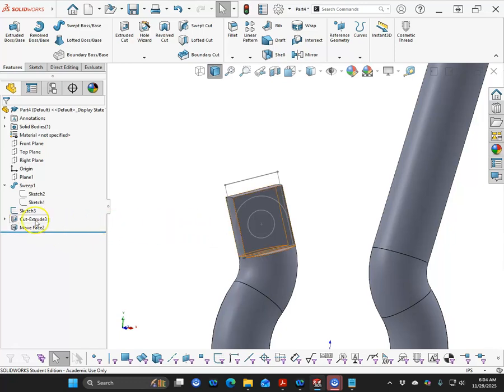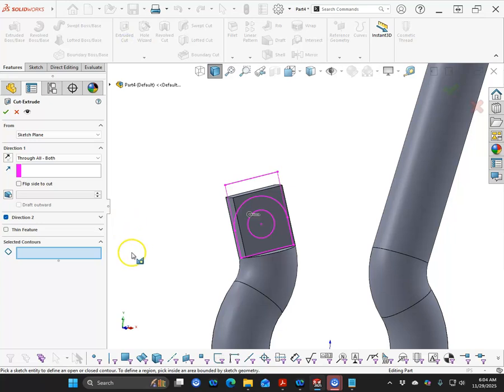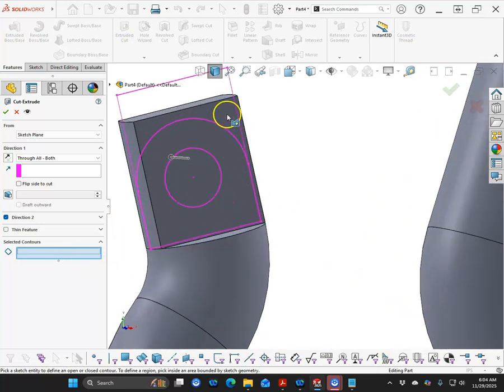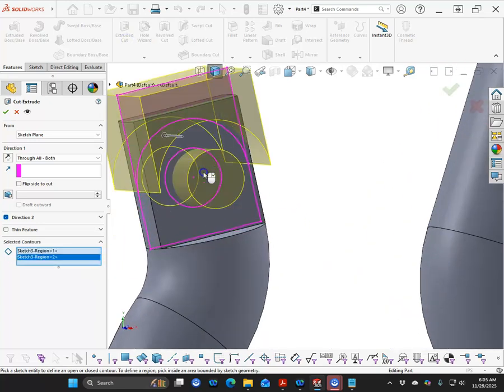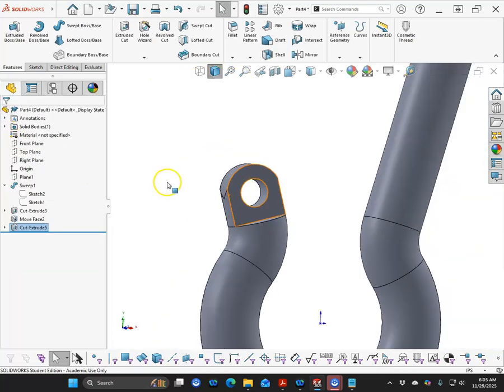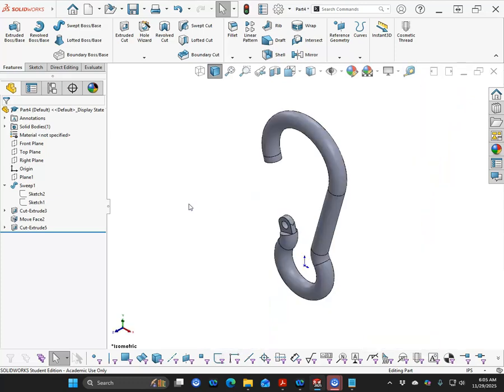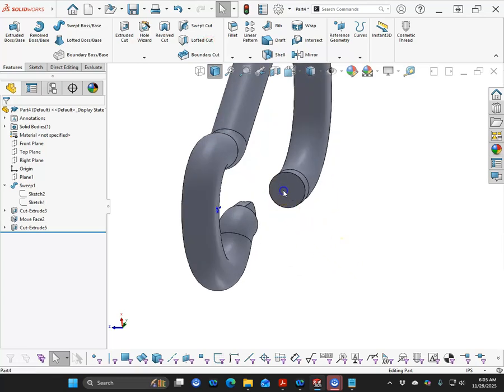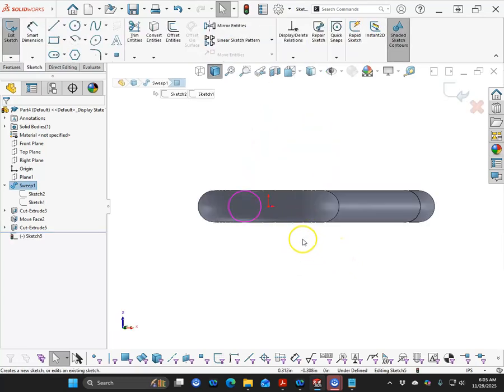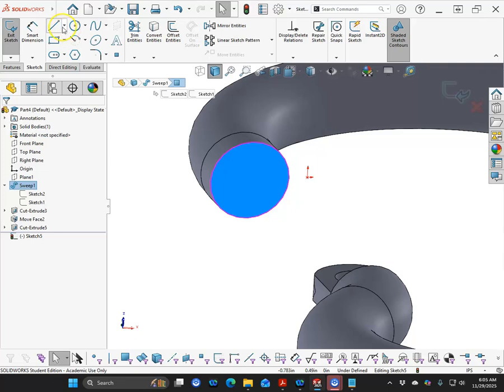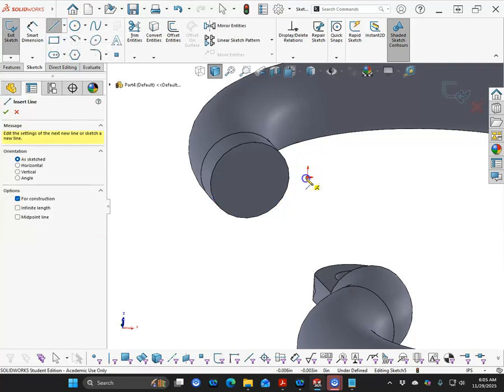All right, we've got that cut. We need sketch 3, extrude cut, and then we're going to pick the region, and we end up with that weird looking thing. All right, so sure there's an easy way, but the first time you go through, boy, I'm not really seeing that geometry. So this should go a little bit easier.